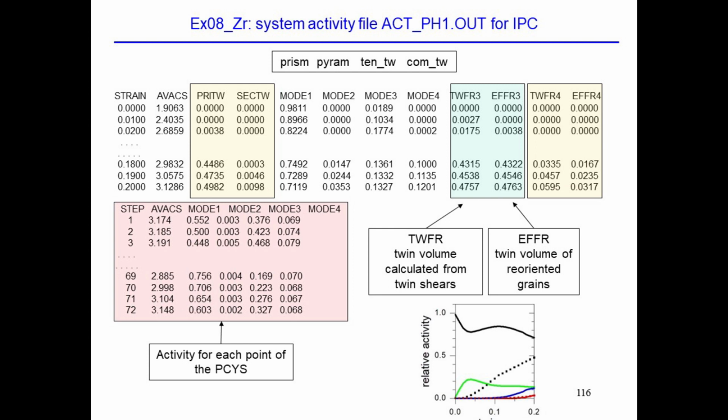That is very interesting to analyze. In this yield surface, 72 points were used. So every 5 degrees over a 360-degree circle in the sigma 1, sigma 2 space the material was probed with strain rates, and each of those points, of course, is a completely different state of stress, and so it activates completely different combinations of systems.